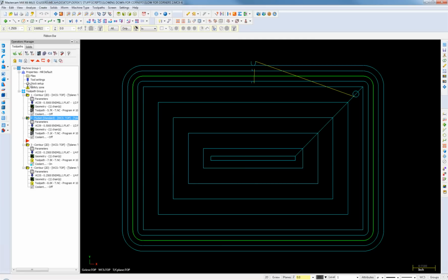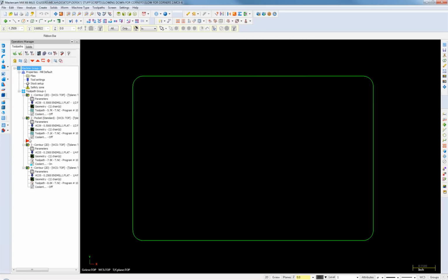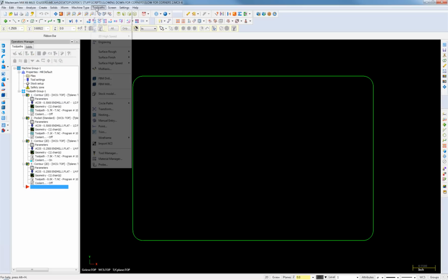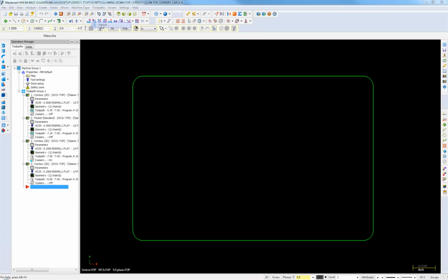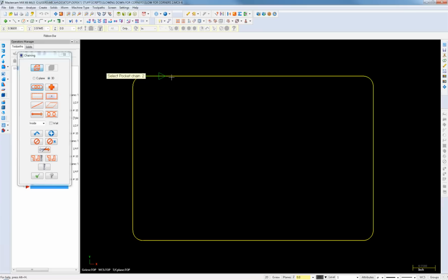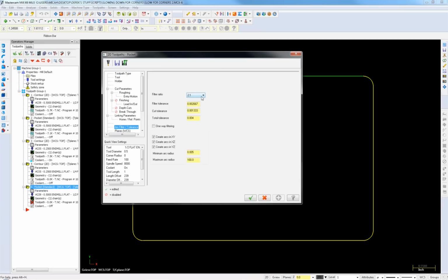So now let me go ahead and turn all these paths off. We'll drop this guy down there. Now if we do Pocket Toolpath and click on the arc filter tolerance, it's already turned on. Right. It must have pulled that default from the earlier operation. Right. If you hit one of the top buttons in there and reload the defaults, it should load it.